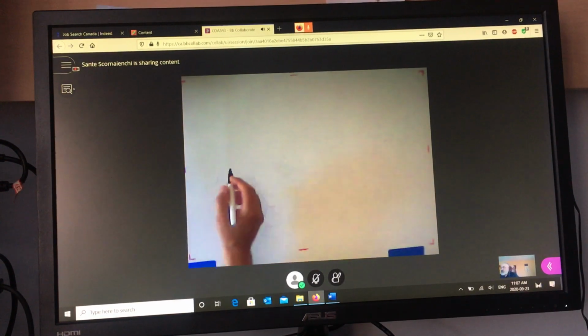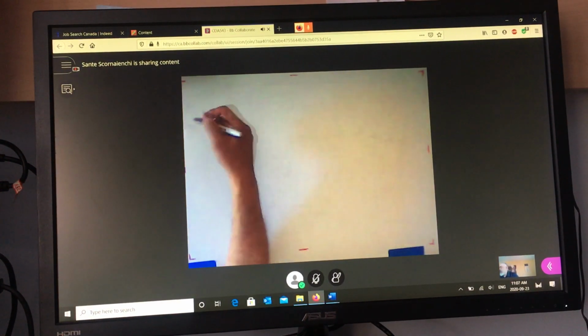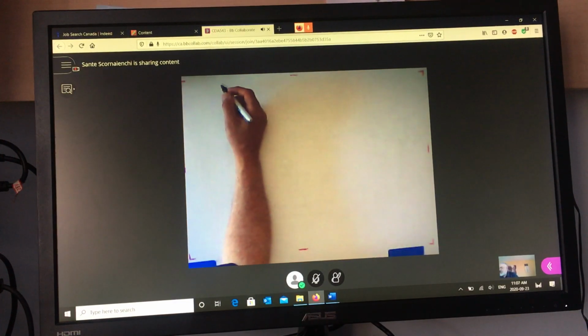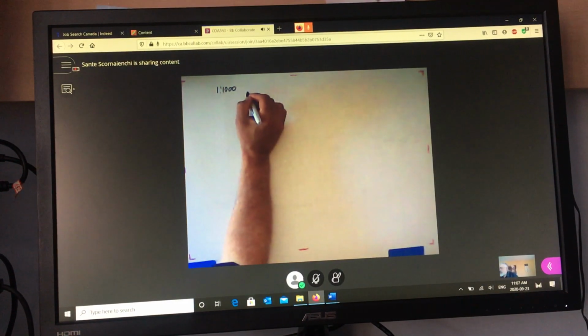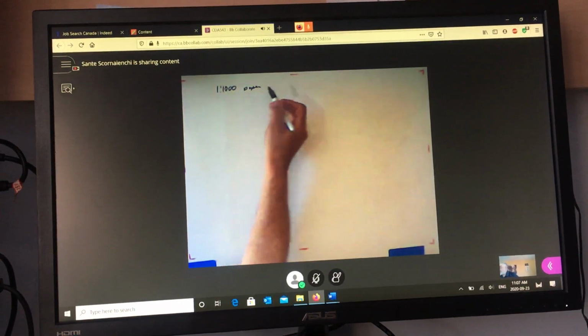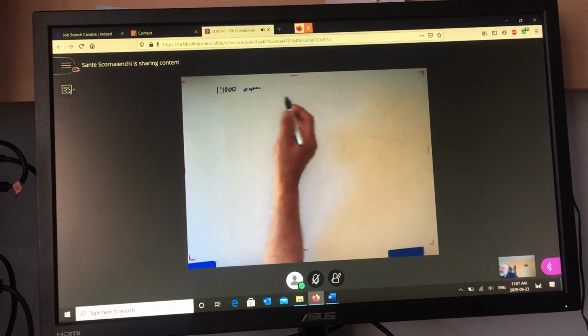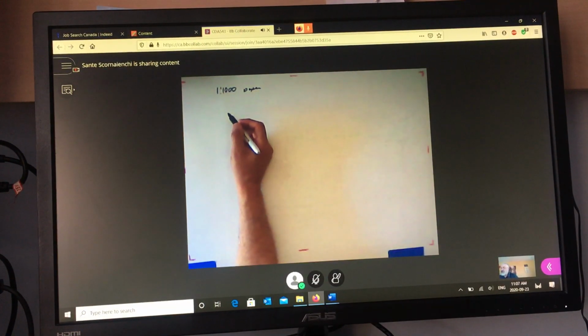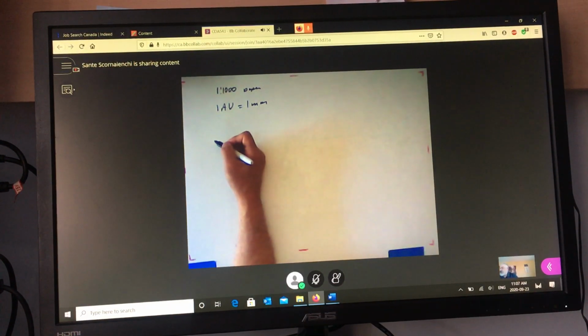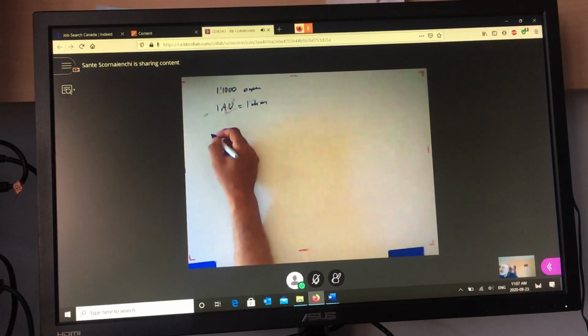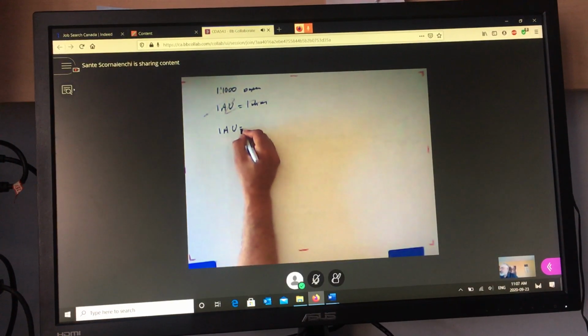So in AutoCAD, AutoCAD was invented and originally used by a lot of architects. So when they wanted to plot on paper 1 to 1,000, that's the plotting scale that they were taking, because they draw everything in millimeters. Okay? So on screen, 1 AutoCAD unit equals 1 millimeter if you're an architect. Okay? Well, we're not architects. We're using 1 AutoCAD unit equal to 1 meter.